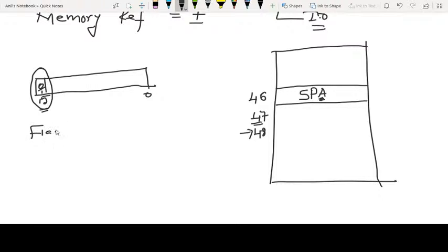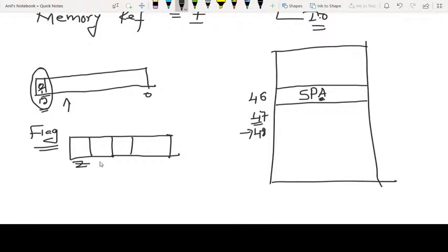If you remember, there is a flag register in the system which shows the status of the program. I explained this already. Every time an operation is performed due to the execution of an instruction, the flag register will get updated. I explained several flags, including the important flags Z, S, C, and V: there is a Z flag, a sign flag, a C flag, and a V flag.